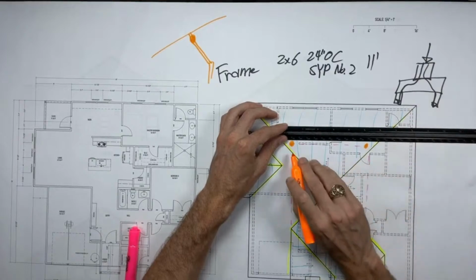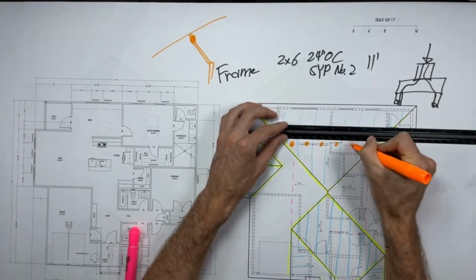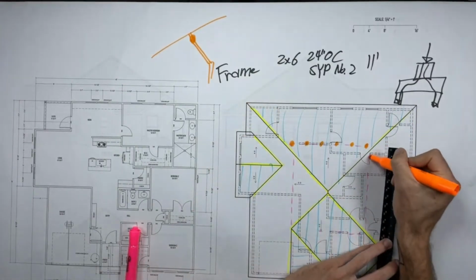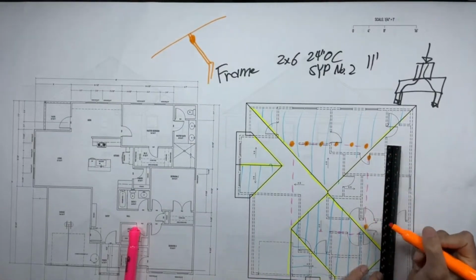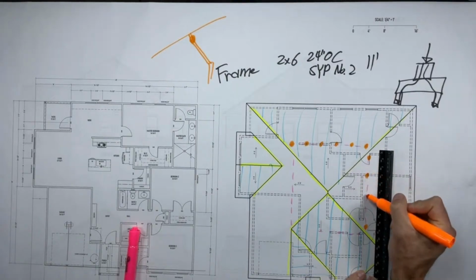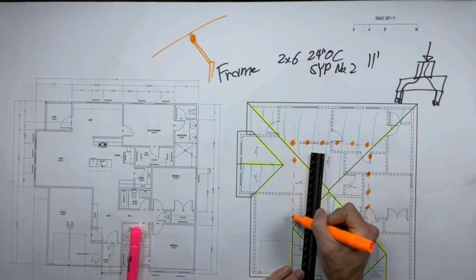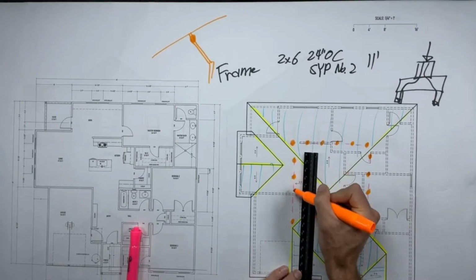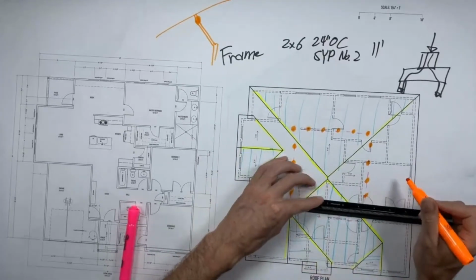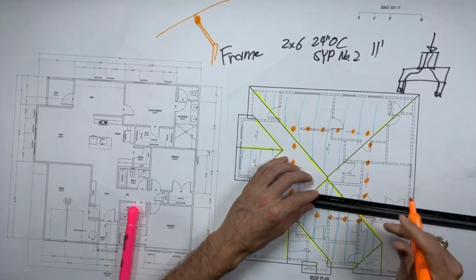And I don't quite know yet, and this is about 20, so I think basically that's the right spacing. And put one on the end, put one on the end. It's about 16, so I'm going to stretch them just a little tiny bit. So they're about 4 feet. It's good enough. And this is 16, so I'll do these basically right at 4 feet on center, like that. And this one, same thing. That's basically 12-ish feet. So we'll just do it like that.